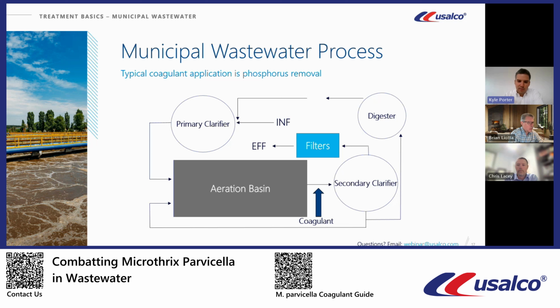But again, if you find you don't have a lot of contact time, or let's say you're in something like an SBR where it's all in one box, you throw it in the react phase, but it's not the end of the world if you have to even put it at the headworks. It's just not necessarily always as cost efficient. But that's true, by the way, of any coagulant, not just for the sake of Microthrix. That's true of anything, PAC, alum, you name it.